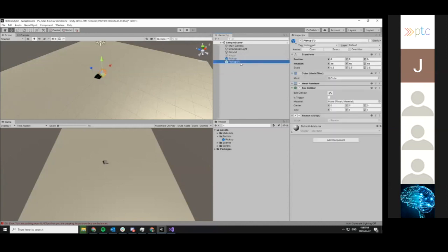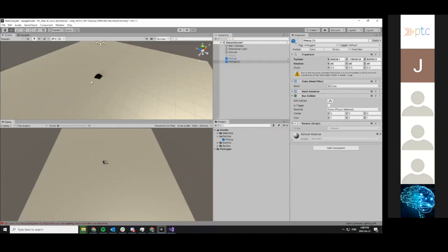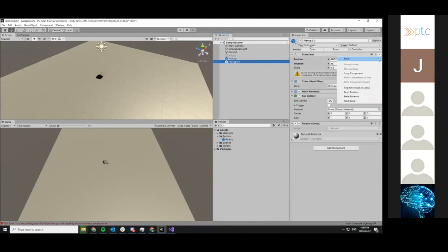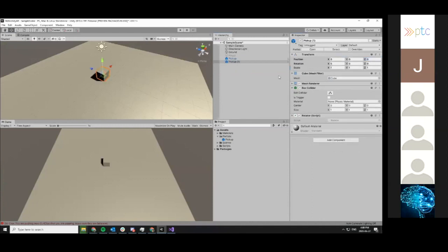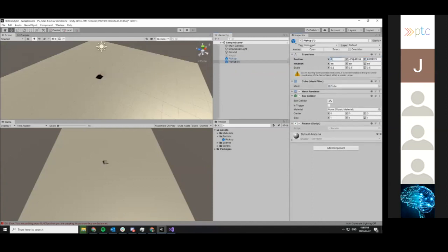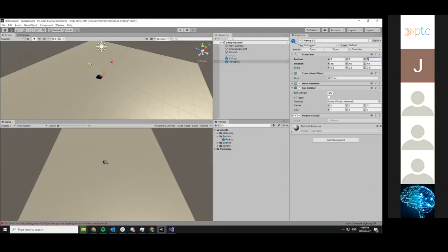And this creates another one. Now, make sure you have this setting set to global if you want to be able to drag it around. If you set it to local, you won't be able to drag it around flat relative to the ground. So, let's bring it back. I don't know why it vanished into the board. All right, so now you can drag it around with global.